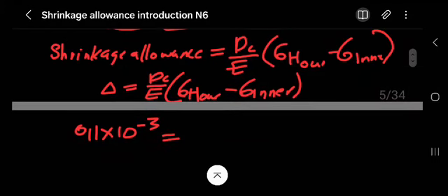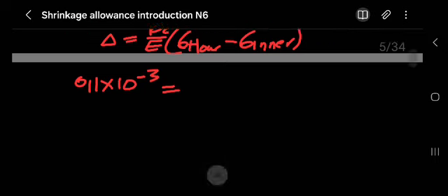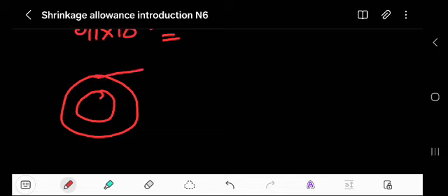Your common diameter, remember guys, here we have this. I want you to check something. It's a sleeve, our cylinder here. Remember, when we're calculating A and B, we focus on the cylinder, not on the shaft. We're given the outer to be 150 millimeter, and the inside diameter to be 119.9 millimeter.